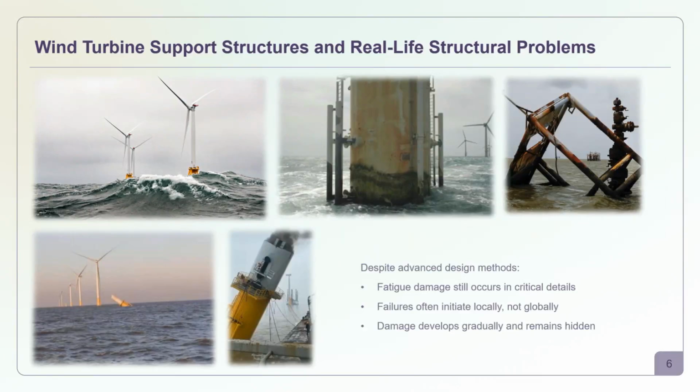As a result of millions of load cycles from the wind, from the waves, and so on, this damage might initiate and evolve before it is even visible from the global level. And over time, all these damage zones can continue to grow, and eventually it can become a real problem, causing big cracks, which will then lead to expensive repairs or can even cause structural failure. And this is why identifying and verifying these zones early is very important.